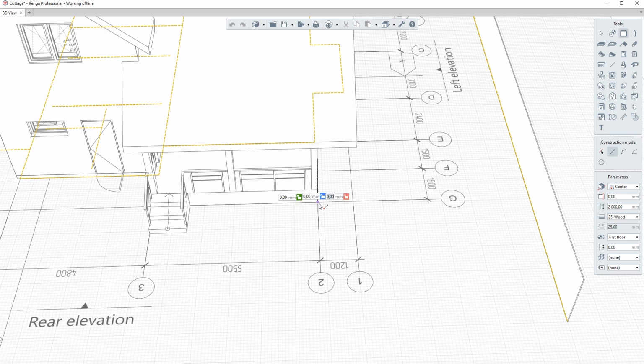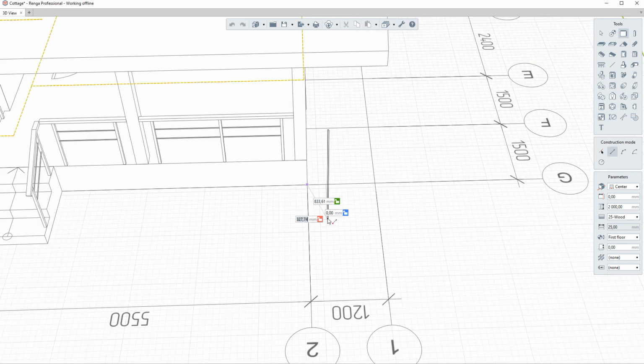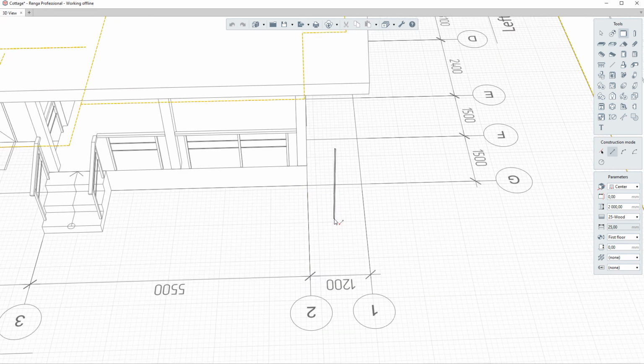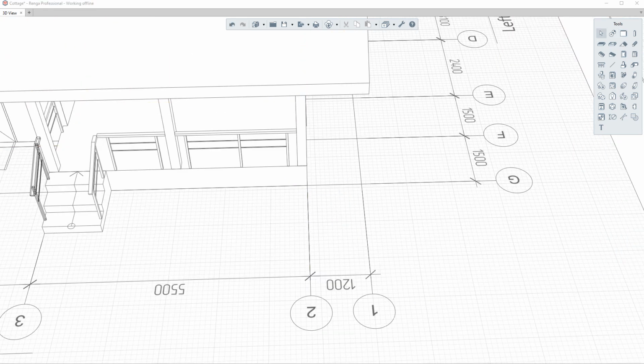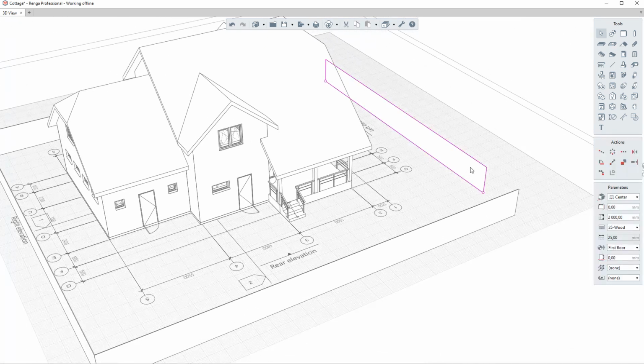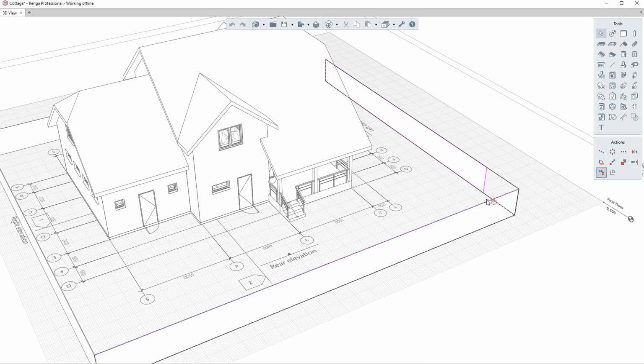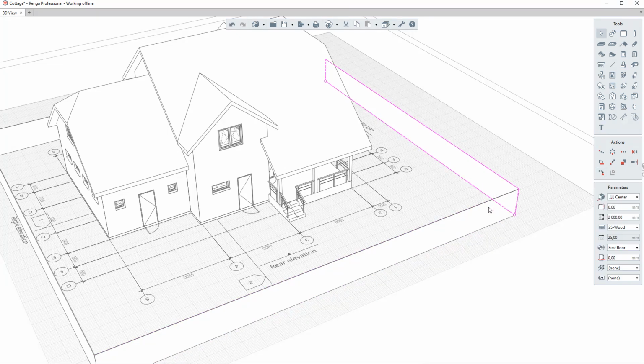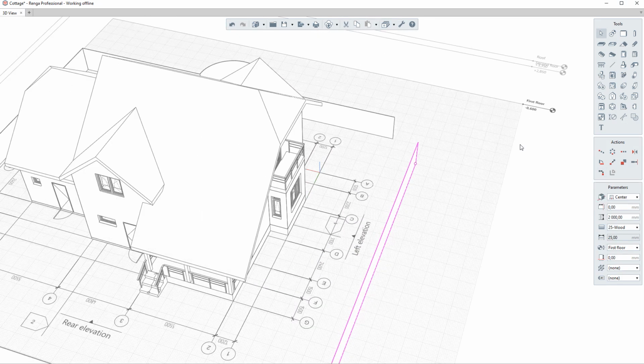If you activate a snap point and need to deactivate it without interrupting the construction, hold the pointer onto the snap point. To complete the construction, click on the first wall and activate the command Trim or Extend to Corner on the Actions panel. Specify the baseline or edge of another object. Left-click to fix the objects. Repeat the steps with the remaining wall.